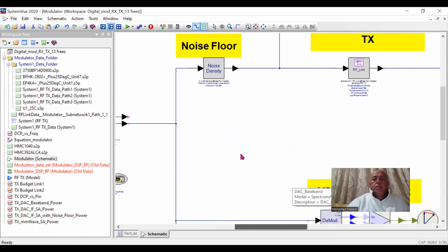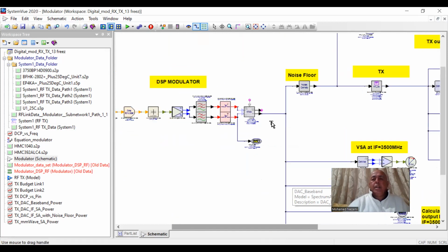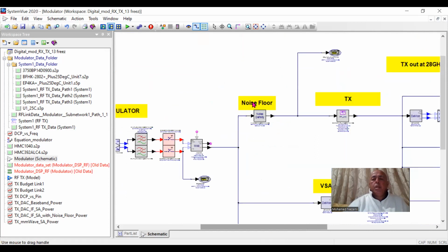After that, we take this signal, and of course, realizing that this is numerically generated, we have to set the noise floor to mimic the DAC power spectral density, which at this point, as you recall, for the 9081 chip from ADI, had a minus 155 dBm per hertz distribution.